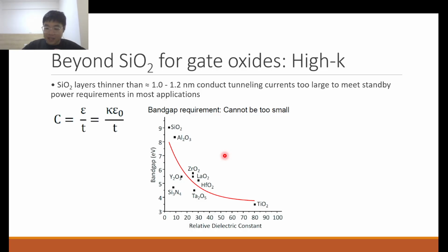However, it's to be noted, and you can read this in research papers available on Google Scholar, that the direct interface between silicon and HfO2 is not a good interface, with a lot of formation of dangling bonds. And as I mentioned earlier, dangling bonds can act as charge traps, which degrade the mobility of charge carriers through the channel. So what is the solution?